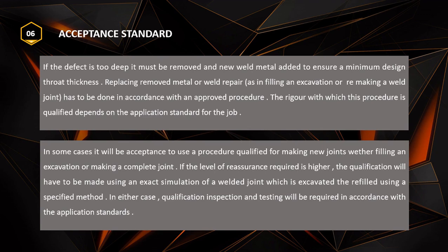In some cases, it will be acceptable to use a procedure qualified for making new joints, whether filling an excavation or making a complete joint. If the level of reassurance required is higher, the qualification will have to be made using an exact simulation of a welded joint which is excavated and refilled using a specified method. In either case, qualification inspection and testing will be required in accordance with the application standards.